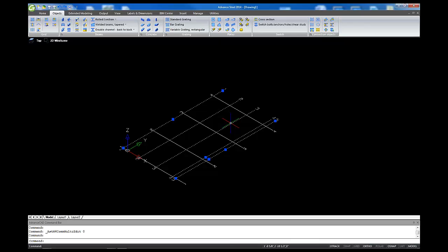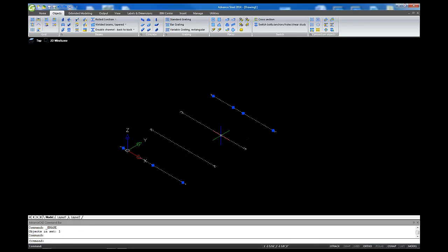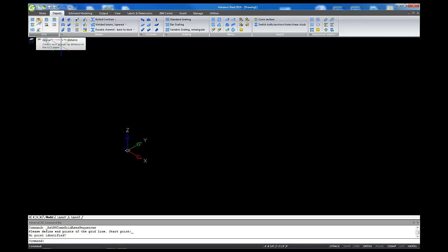All right. Let me ask you a question. When I want to open, I'm back in Advanced Steel now. So I hit new, and then it gives me this select template file. You have the mm_template, and you have just template. The mm_ is metric, and the other one is imperial.